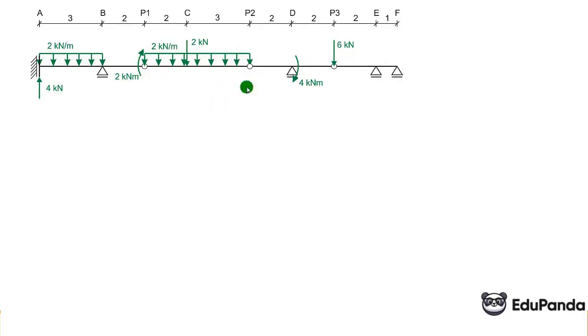All right, let's look from the right side. Here we cut the joint. We have a vertical reaction at the joint. So on this beam from P3 to F, there will be one vertical reaction, a second and a third. All right, so it is not determinable. Let's look at this from P2 to P3. One vertical reaction, a second vertical reaction, and a third vertical reaction. It is not calculable. The beam P1, P2. Here there will be one vertical reaction and a second vertical reaction. Okay, this one is calculable, so this will be the main one.